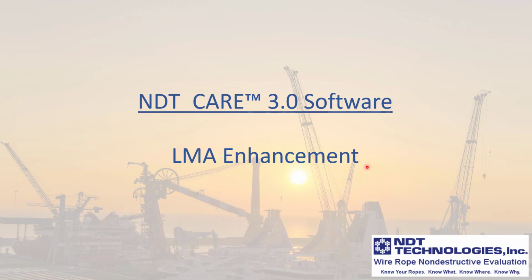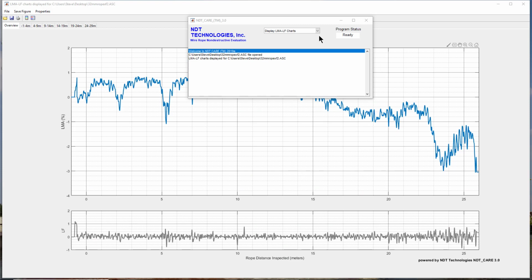LMA enhancement. We can now enhance the LMA data to reduce or eliminate various inspection artifacts caused by the inspection. To do this, the user will select the appropriate sensor head as part of the test equipment. From the drop-down menu, we'll select LMA enhancement, and a pop-up menu will appear for us to choose the sensor head. In this case, we used an LMA 250 to do that. So we'll select that sensor head.